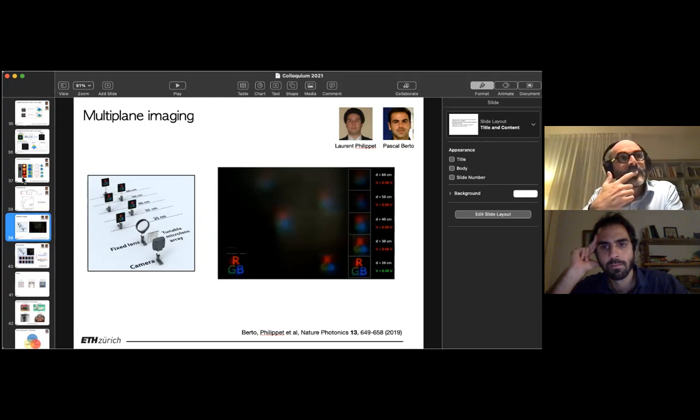And here the transmission is on the order of 60-65%. Now what we're doing, and we have a new student working on that at the moment, is using ITO. And now we reach levels of rather 85-90% transmission. So this is becoming better.